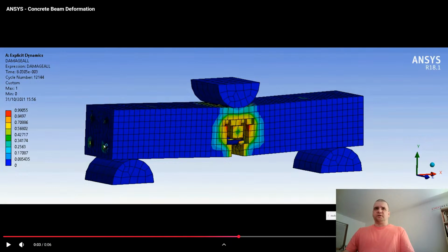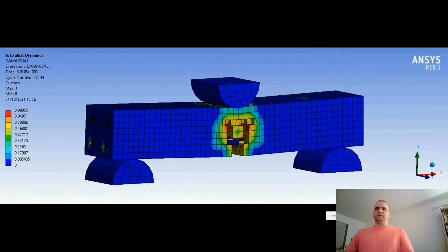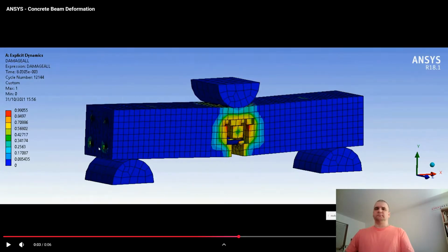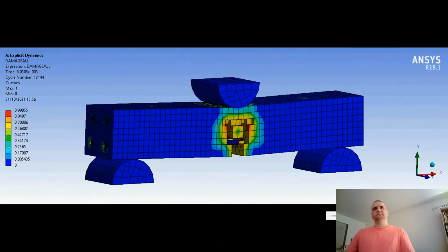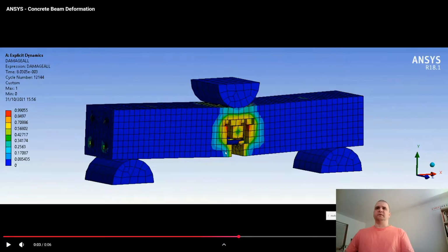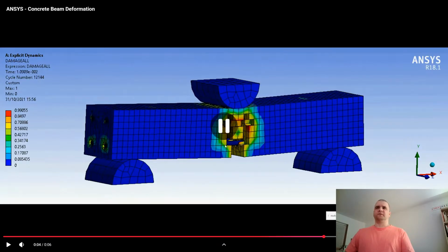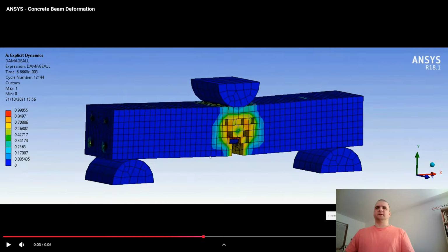But judging by how it breaks the bonded contacts between the rebar and the concrete, I think it's fully modeled. Judging also from the mesh of the rebar, it's not a software reinforcement, because the reinforcement usually is made with line bodies in ANSYS.